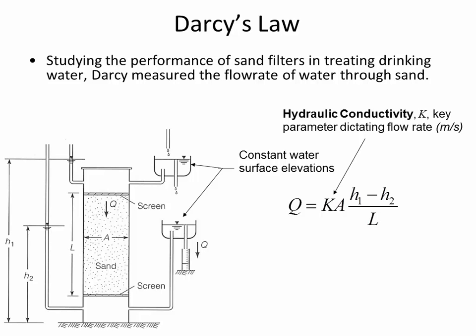And that's what Darcy's law gives us, an expression that relates this soil property to the flow rate of water through a soil. So in the case of infiltration, if you want lots of infiltration, then you want a soil with a high hydraulic conductivity, because it doesn't require much of a head differential to allow large quantities of water to move through it.